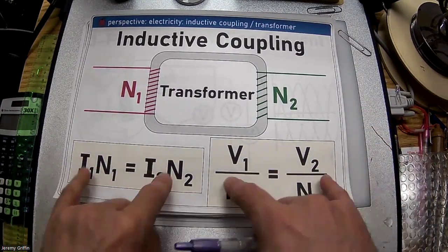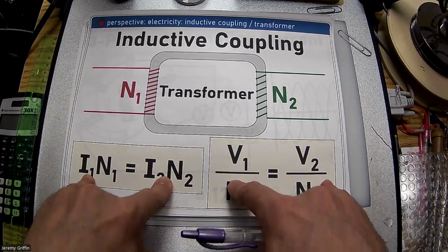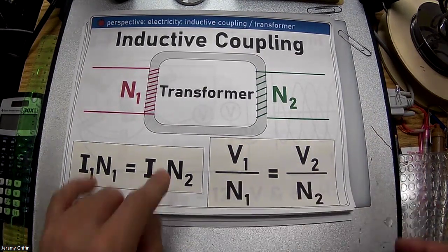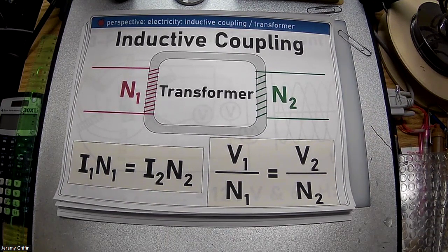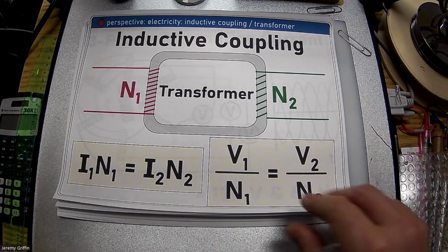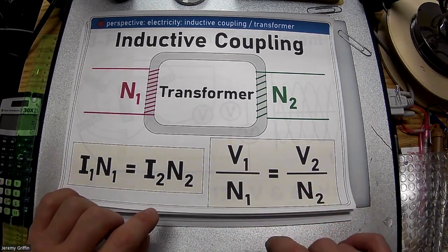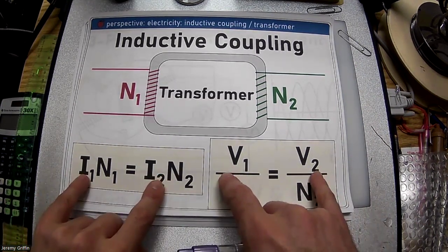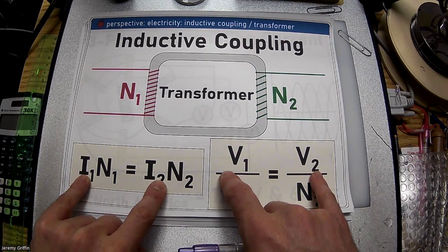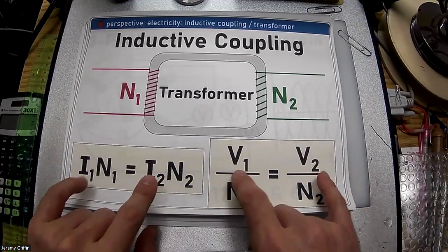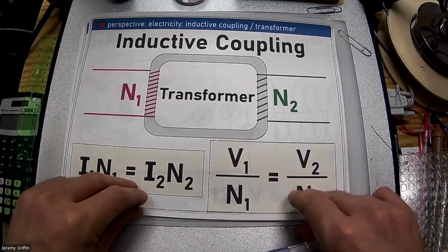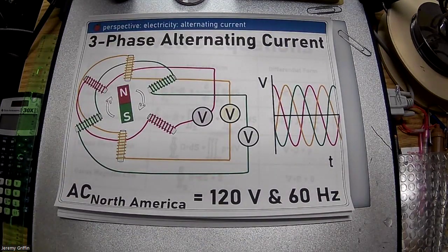If you put these two together, you can show that power is conserved, which is energy per time. So that also goes hand in hand with conservation of energy. You aren't creating or destroying energy. You're just stepping up or down the voltage, and then current does the opposite. You guys remember Joule's law, P equals IV? That's how you can prove that energy is conserved. Power is current times voltage. I think I showed you guys this the other day.